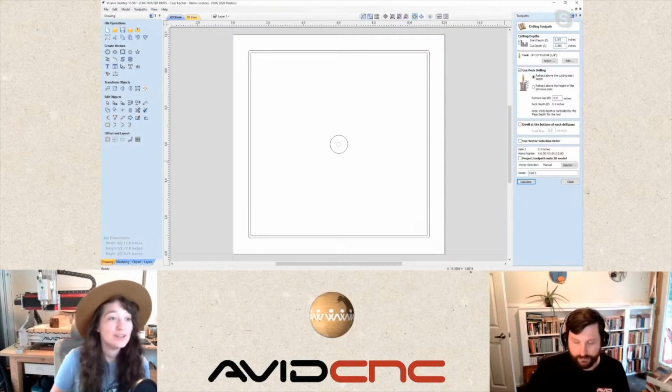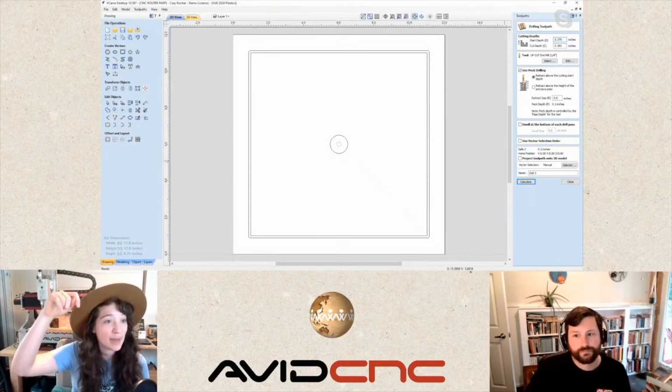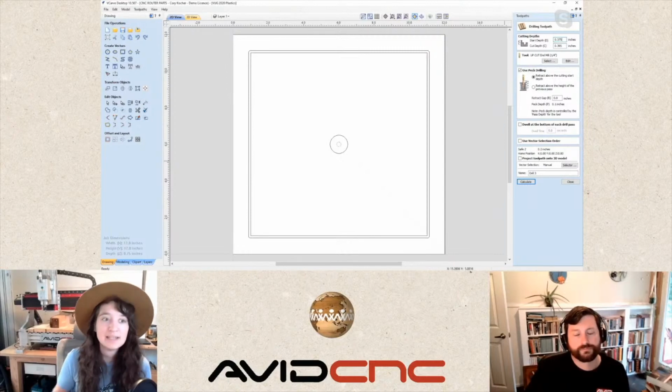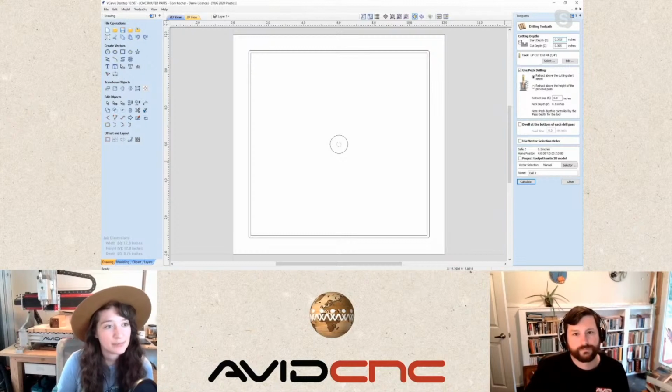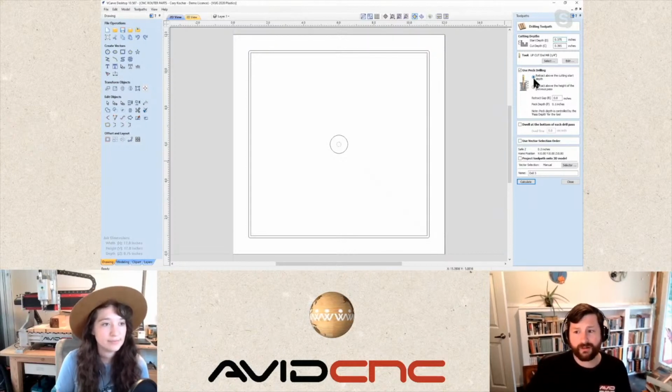Definitely. So I love that you can utilize the Peck drilling where it touches down and lifts back up, and then it continues to go down at the set pass depth. But it really gives an opportunity for those chips to come up and out and not create too much heat. Yeah, so you could use that helical style profile toolpath like we talked about in the plywood. But if we have this upcut tool already loaded in and we want to do this, we can use Peck drilling. And so I do like to retract above the cutting start rather than just from the last previous height.